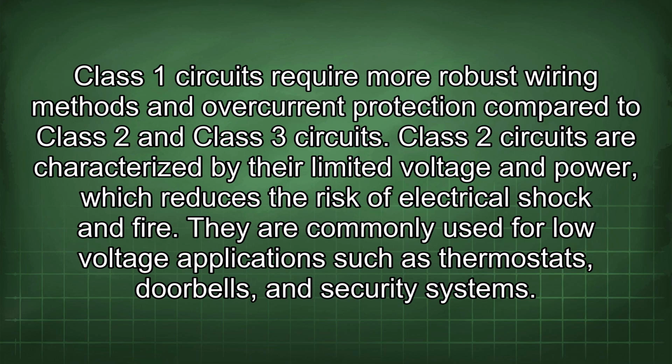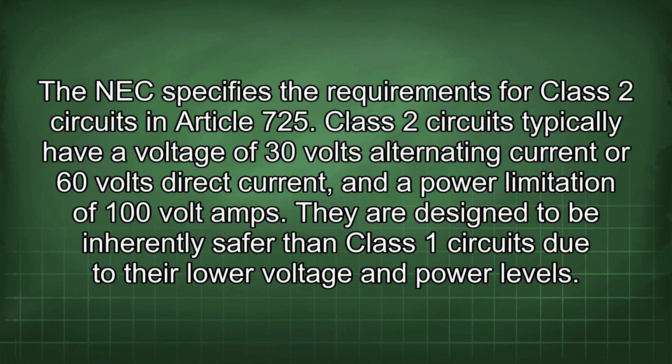Class 2 circuits are characterized by limited voltage and power, which reduces the risk of electrical shock and fire. They are commonly used for low-voltage applications such as thermostats, doorbells, and security systems. The NEC specifies the requirements for Class 2 circuits in Article 725.